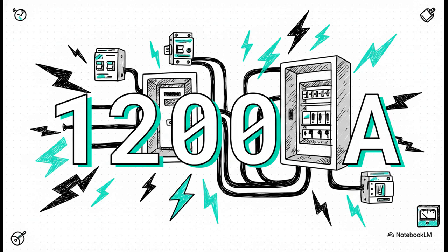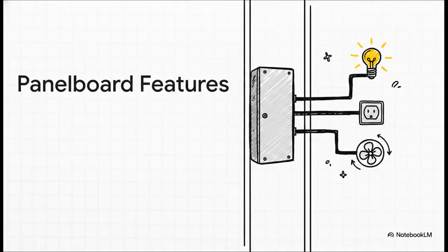But in standard commercial practice, 1,200 amps is typically the maximum incoming main capacity you're going to see for a panelboard before you're forced to upgrade to a heavier class of equipment. Because of that lower capacity, their limited depth, and the fact that they're front access only, a panelboard's real job is handling final end loads. They are completely optimized for downstream branch circuit distribution.